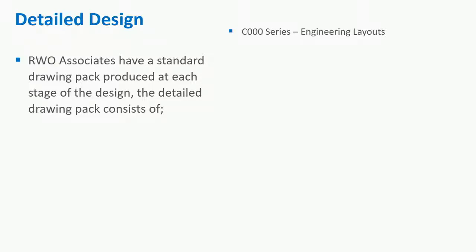There's a separate label set that's applied to the engineering layout, which reduces the amount of information that's typically shown, so the drawing's a lot more readable, so it's less busy. You've got your levels drawings, which is your finished floor levels, your threshold levels, your roads, back of footpaths, any other information that you might need to show there. Your drainage drawings is typically your drainage plans, your adoptable drainage, your plot work drainage, which is all built within Civils 3D. You've got your manhole schedules, impermeable area, catchment plans, any other information regarding SUDs that you might want to show or the developer might require.